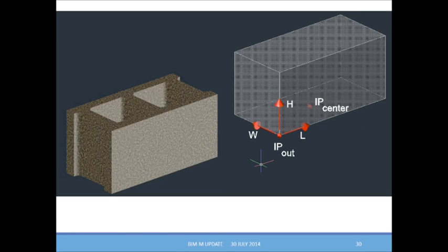And when I use the word bounding box, a lot of BIM models, and I'll show you one in a second, basically, you don't want to see all the complexity of the masonry unit in the BIM model. That may be unnecessary, too much detail. And so, in fact, we can represent the unit in a BIM model as just a cube. And in terms of storing information about that cube, we need to store some insertion points, either maybe the corner of the block, that's what I call insertion point out, or maybe at the bottom of the block at the center of the withe in which it's going to be inserted. Because remember that the masonry unit model is ultimately going to feed into a masonry wall model, and we have to know how to automatically insert these blocks into the masonry wall model. So we're going to store the bounding box and the insertion points of these masonry units.